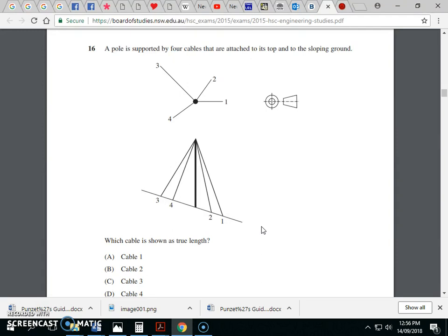Glare is a composite. Yes, it has aluminium in it. Exactly right. Glass laminate reinforced aluminium, resin, epoxy. Okay. And I'm not sure what the composite is made of in the 787, but I know that a feature is that they're predominantly composites. Carbon fiber, maybe. There definitely is carbon fiber. So, for instance, the propeller blades are carbon fiber. But I'll leave that as research for you guys to send to me to the group chat.